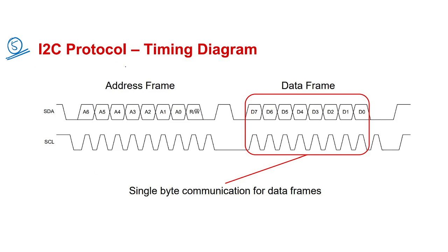So at a time you can send, this is serial communication. Serial communication means there are two types of communication. Suppose 10110110 is there. One bit you are sending, one bit you are sending. This is nothing but serial type of communication, like SPI communication, I2C communication, UART, universal asynchronous receiver and transmitter. These are nothing but serial type of communication. Suppose each bit is transmitting at 1 nanosecond. To send 8 bits of data, it will take 8 nanoseconds.